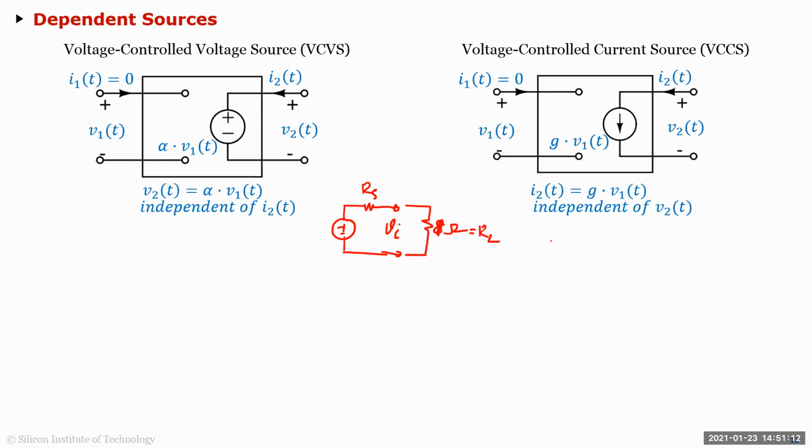1 volt, right? V squared over R. So P out is equal to V squared over R, so I need 1 volt peak. Let's say this was 100 millivolts. So you'll say, okay, I'll just put a transformer. I'll take my cell phone, I know this is 100 millivolts, so I'll do a transformer 1:10, right?